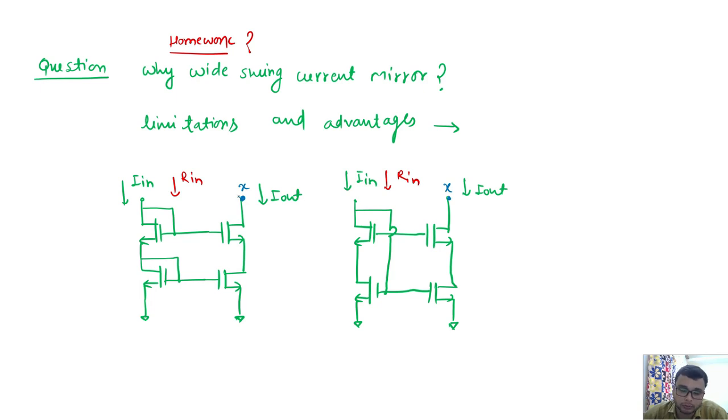If we are losing any extra voltage, then we can see, because we have a fixed amount of VDD. In any structure, whatever design we have, we may have a design of 1.8 volt. We always have the fixed VDD rail. We always have some value of VSS, maybe here 0 volt, and in between we have this room of 1.8 volt. And out of this 1.8 volt room, if we lose more in the current mirror and input pair just to keep them in saturation, we will get very little swing. I'm talking about this in the sense of an amplifier.